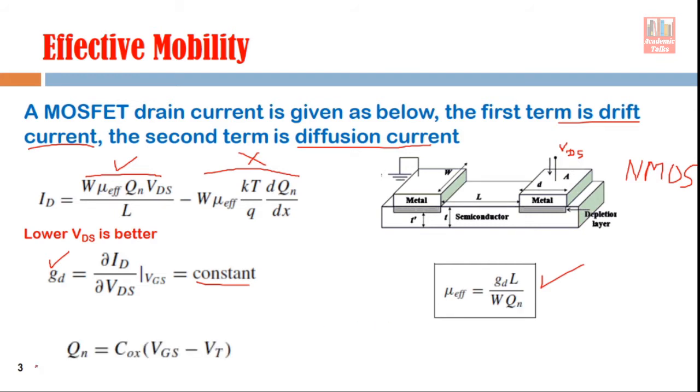That will be calculated with the help of this kind of equation. You can see this is a very simple equation, and it is applicable in the case of capacitors also. You know the expression for a capacitor, Q is equal to CV. So this simple expression is used here, right? C is the C part, and V is replaced by VGS minus VT. You know this VGS minus VT is actually your overdrive voltage. Sometimes we call it VOV also.